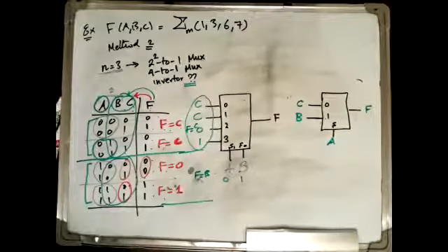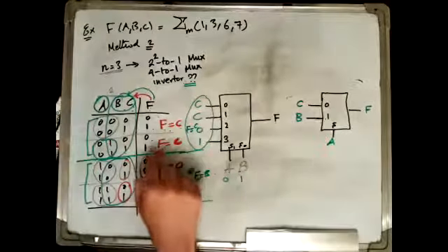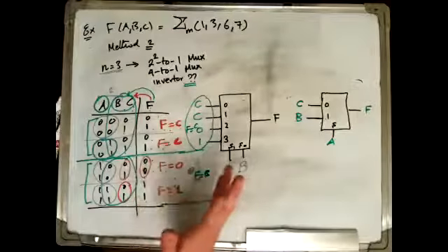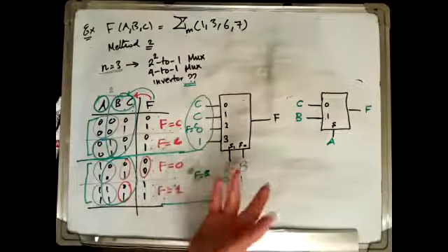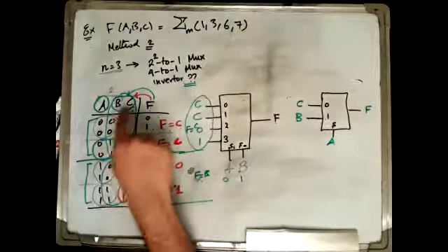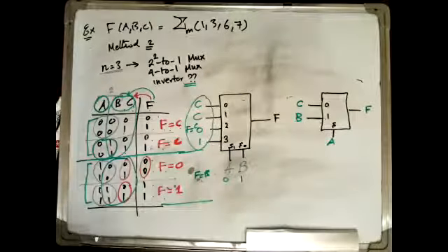We were able to reduce the size of the multiplexer to 2 to 1 without any extra cost. However, for other functions, you might need, for example, an OR gate or XOR gate or XNOR gate. Depends, 2 input. In other words, you will have some function here in terms of the remaining variables, which are B and C.